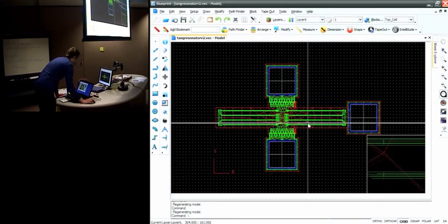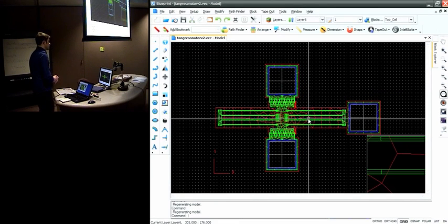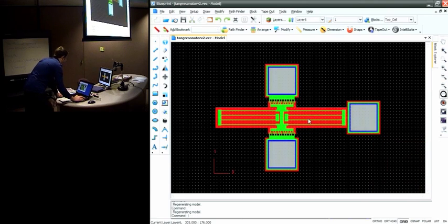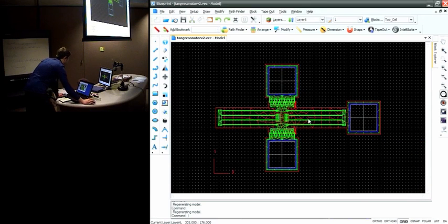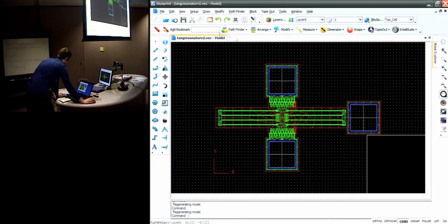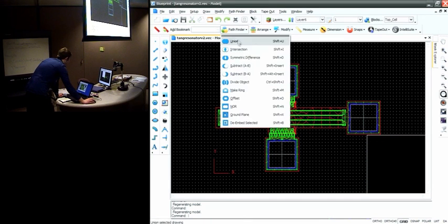And you'll notice that since it meshed our model going into 3D Builder, all of the mesh is still there, and if we want to get rid of that, so you wouldn't notice if you had the layers filled, it would look normal, but without them, it's still there. So what we can do is use Pathfinder. And then we will merge the layers.